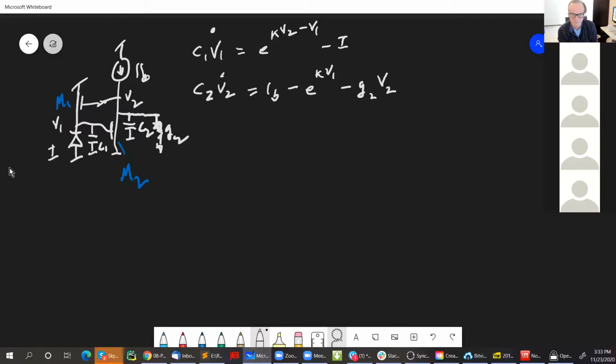Is that helpful? Do you want me to go on and do the small signal stuff too? Then I'll compute the transfer function in small signal as a function of the time constants. I think that's a helpful exercise too, because you have to do some algebra. So let's now write it in terms of conductances. Basically, all you have to do is differentiate these things with respect to the voltages, because the conductance is the change in current with respect to voltage.